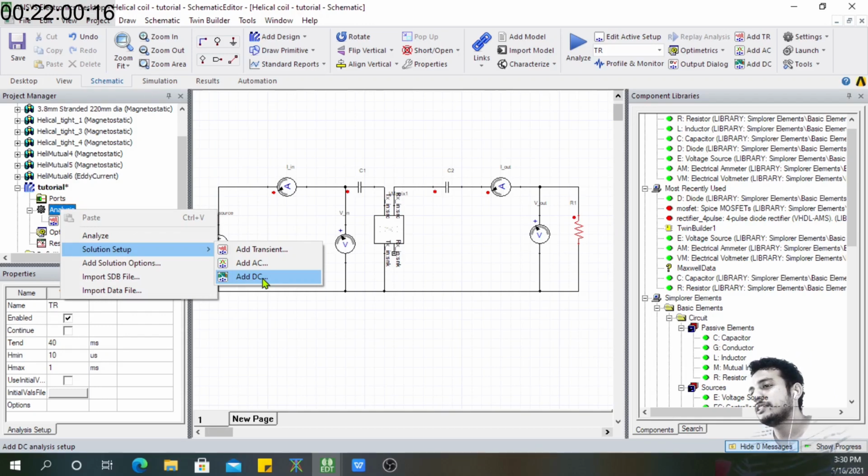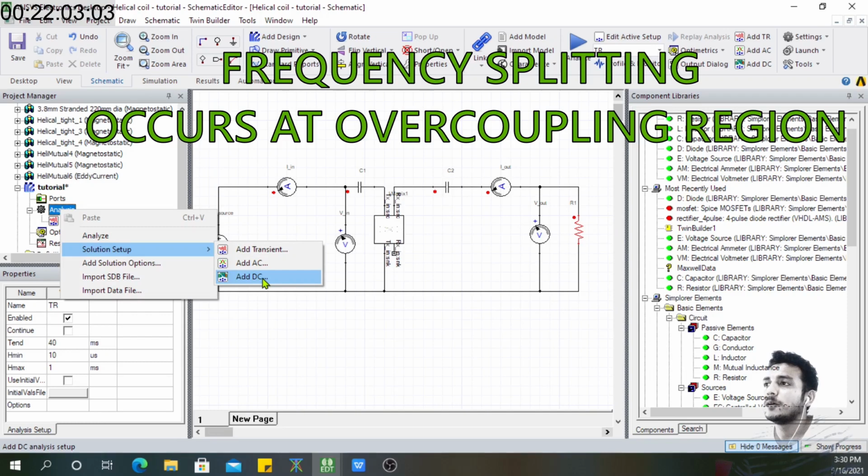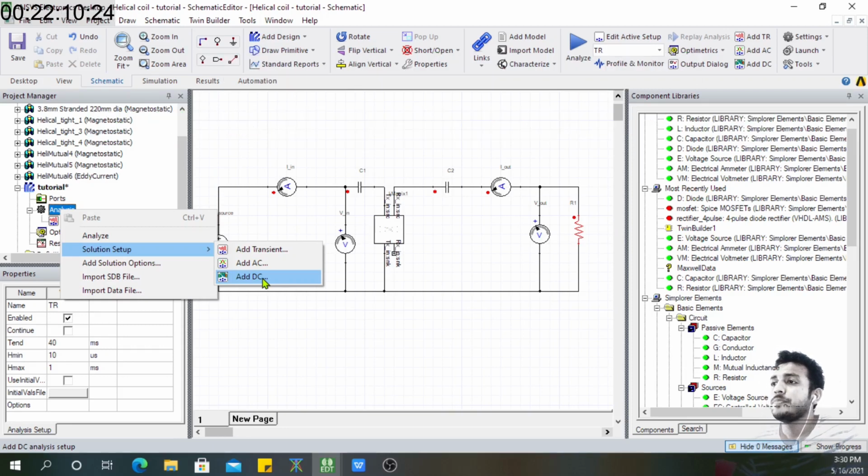What we are exactly trying to observe right now is the frequency splitting phenomenon, one, but more important than that, what we are trying to observe is where the resonance happens, because resonance is very sensitive, it happens at a particular frequency. But now, as you can see, our objective is to resonate at 6.78, because that's what we need, right? Though you can transfer power at any frequency, we do not want that. We want to transfer power at 6.78 because we have designed our system at 6.78.